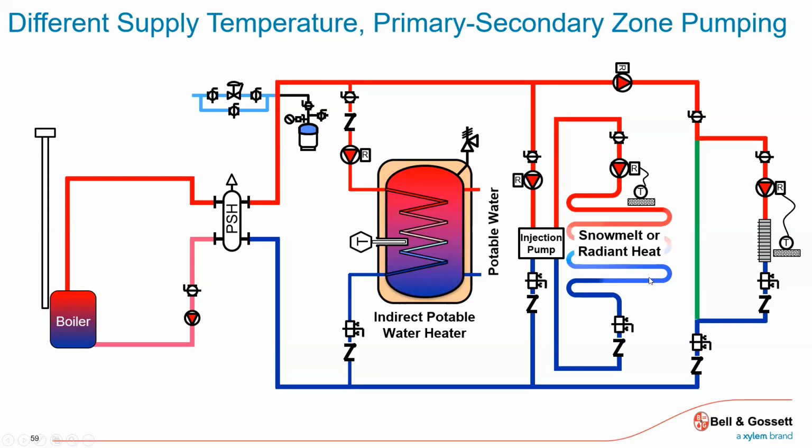So I'm going to have this water moving across this tee. I'm checked, the pump is off. I'm moving along just like a zone pump. I've got 3 or 4 zone pumps. One's running, the other 2 are off. I could have heat going across here, but that heat is not migrating down, and it's not going to be induced by the flow of this pump.